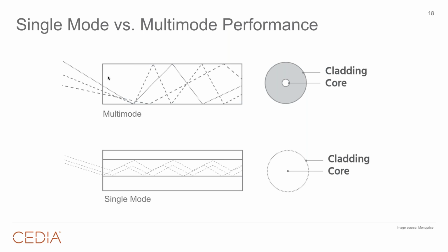That single mode core keeps those light signals grouped much more tightly. The waves are much more tightly grouped. And because of that, we can go longer distances. And when I say longer distances, I literally mean a 4K 444 HDR signal going out 20 kilometers before we start to get out of phase. Now, as I mentioned, single mode doesn't really have a minimum distance. So we can use it in a lot of those shorter run lengths.